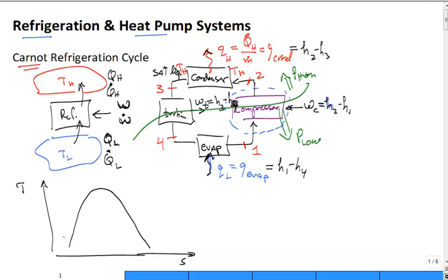So we put a line of constant pressure, high pressure. And the maximum we can get would be, well, it's going to come in right here at state 2, saturated vapor, and going out at state 1, saturated liquid. Not 1, that's 3, isn't it? Get the right numbering here, 3. Does that make sense?